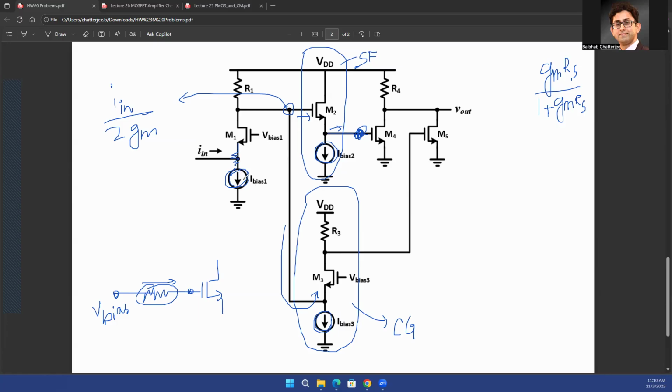But why are you going to use current sources instead of voltage sources? It is majorly because if you use voltage sources, there would always be a voltage drop because of the parasitic resistance in the path or the wire resistance. However, if you use a current source for biasing, the same current will keep on flowing through that resistance. Even at this node, although this is a gate, so of course you cannot bias it like that. But for example, if you are biasing using a current, even if there are parasitic resistances, the same current actually flows through the source. The same current actually flows through the drain, right? Even though there are always parasitic series resistances because of wiring.